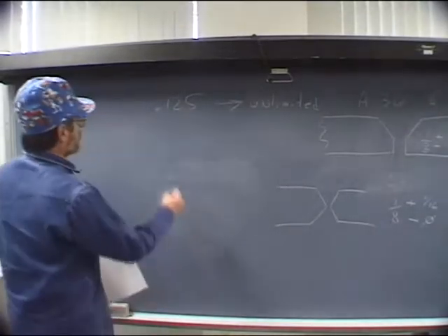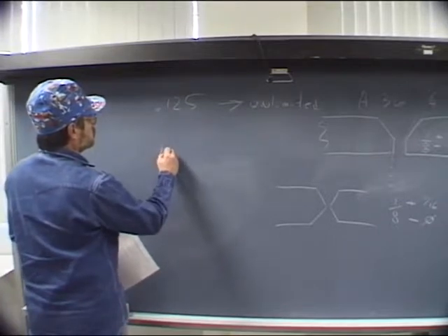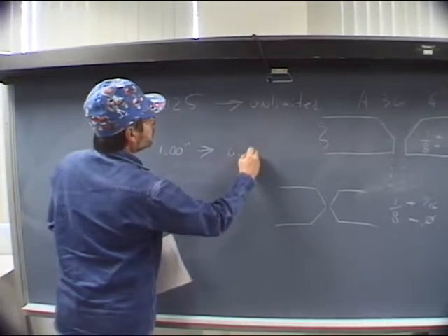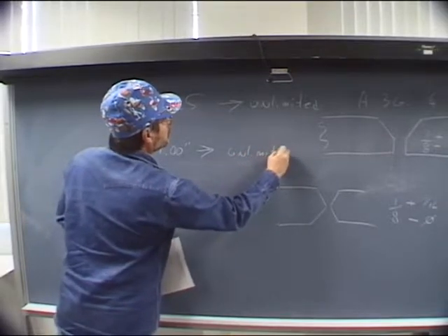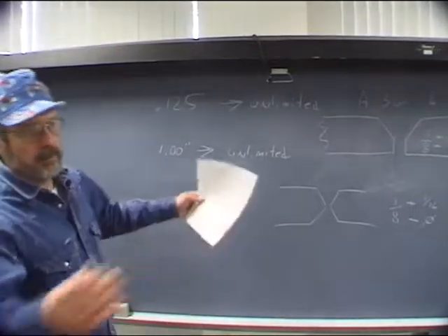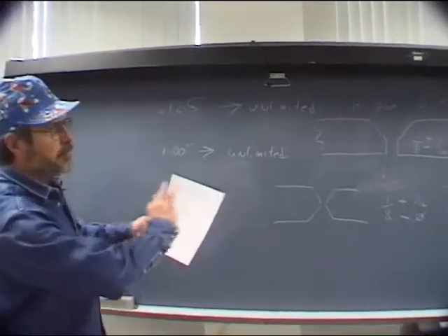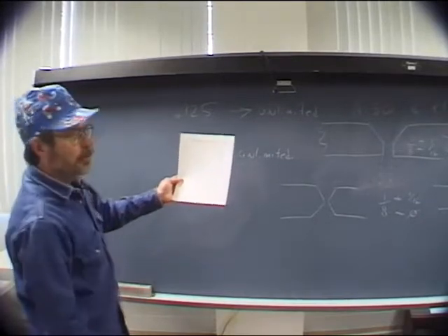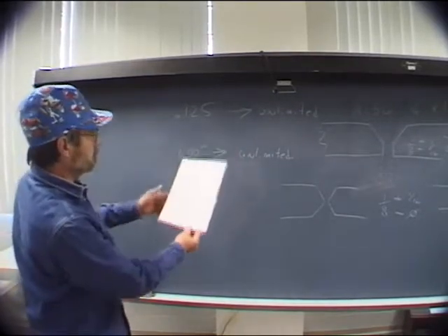The pipe diameter range, 1 inch to unlimited. So this procedure is good for any size pipe. So we're giving ranges again. And again, if you want to know the details, go read QW 403, that paragraph. It'll explain everything to you.